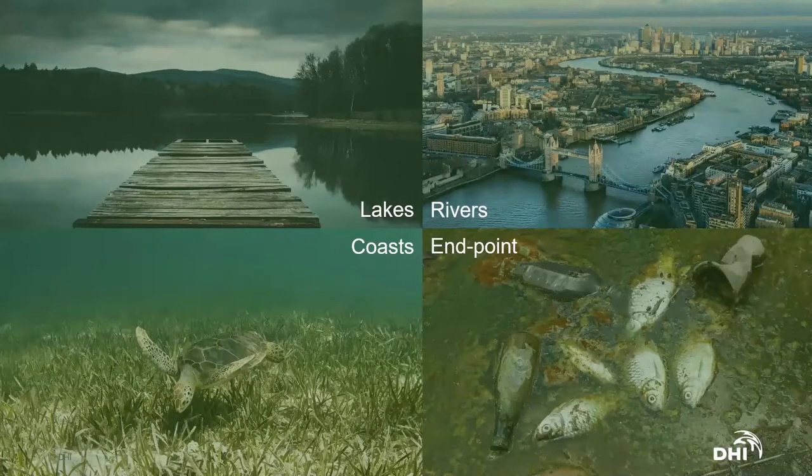The environmental endpoint here is also very important. Are you evaluating the decay of a substance like bacteria or BOD? Then the introduction of internal processes might not be important. If, on the other hand, internal processes are important, it should maybe be an algae growth model. So it's not just decaying BOD, it's also releasing nutrients that then become new algae growth. And then it's very important that you choose a model that can handle those things and not just decaying or degrading organic material and nutrients.